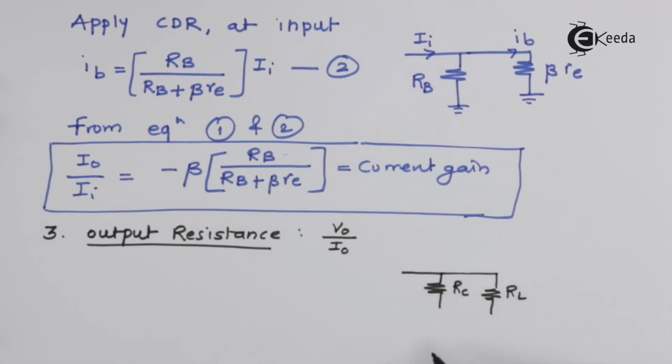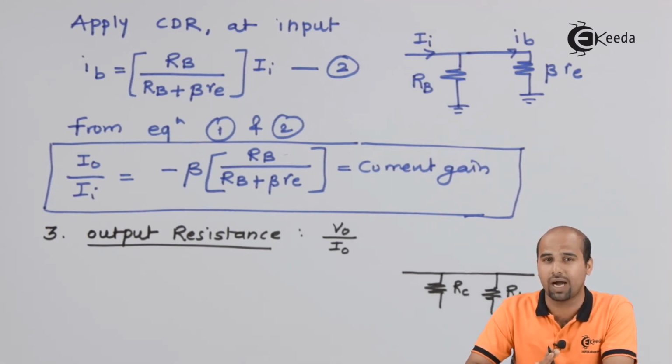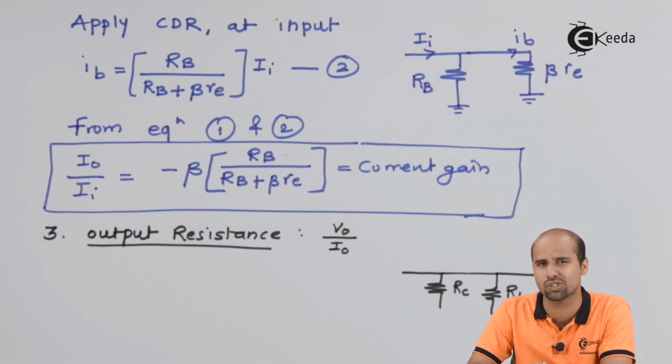We can also have any DC motor, stepper motor, or any kind of load which is supporting all the ratings of BJT. So obviously high voltage and high current load we cannot directly place at the output side of CE amplifier. This is because it has some limitations of current and voltage characteristics.